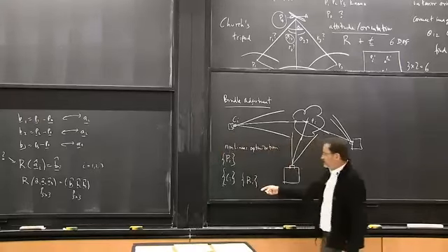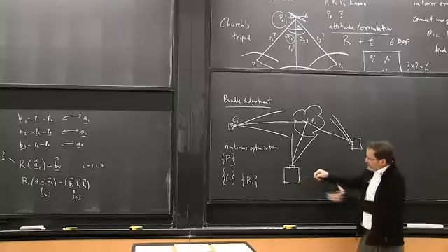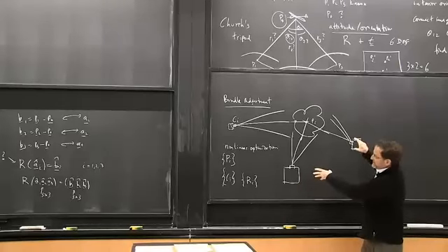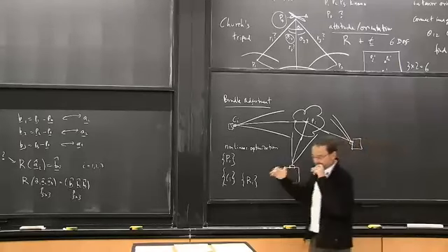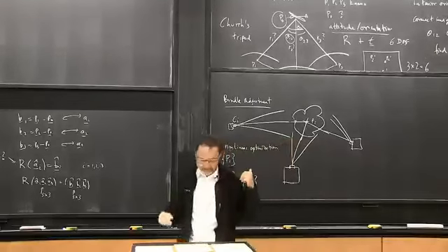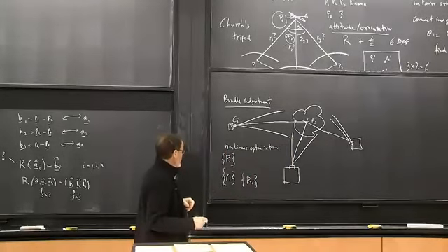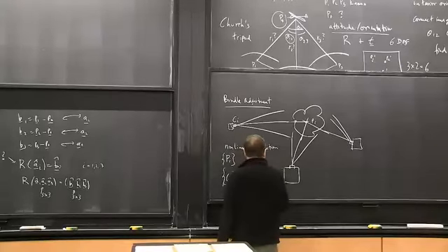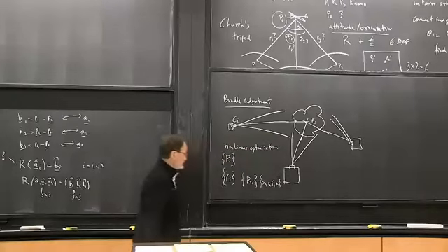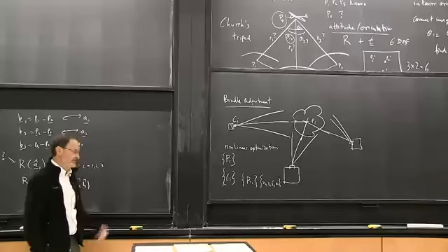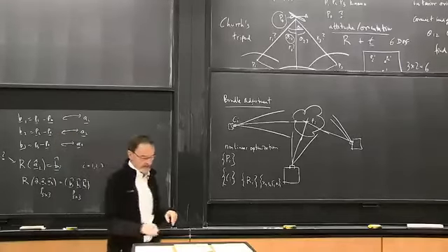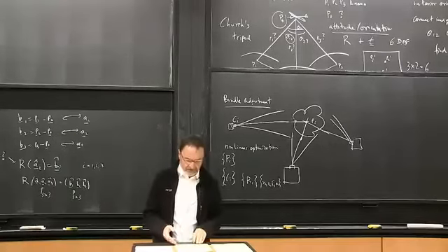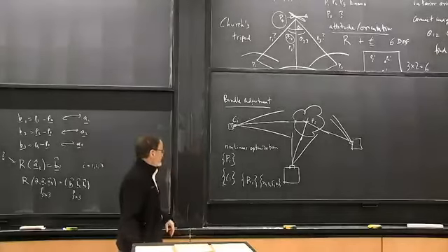I'll just write it that way. So we tweak things to make the errors as small as possible. And again, the errors are the errors in the image, not out in 3D. And so what else? Well, in most cases, we don't know what the camera properties are. So we need to also do interior orientation. And maybe, if we want to be accurate, some allowance for radial distortion.